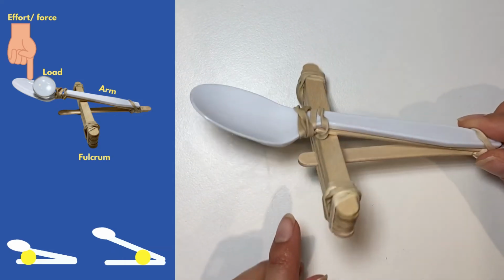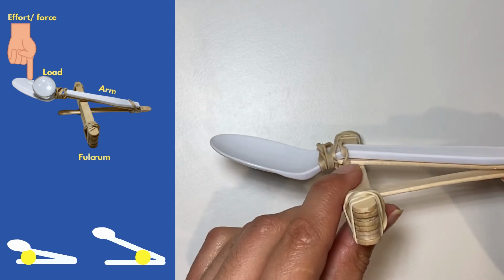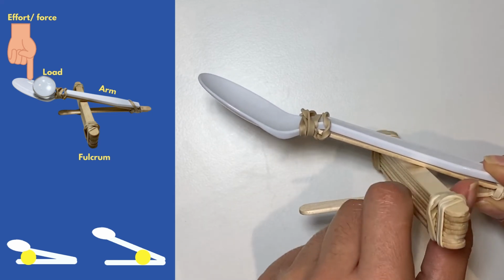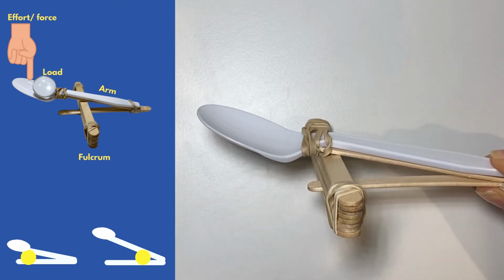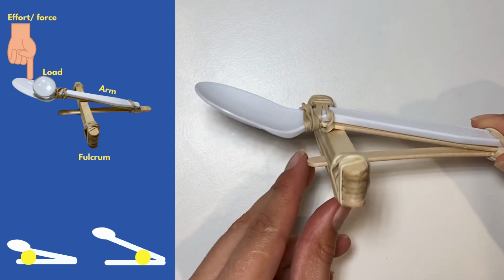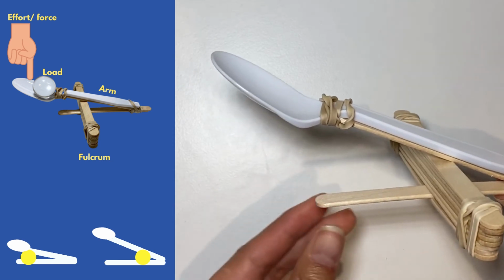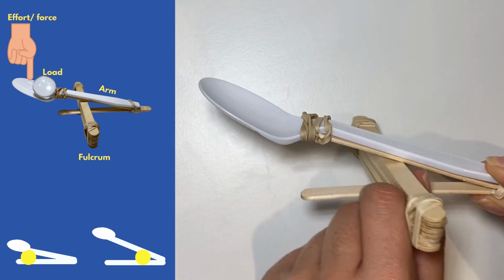Try experimenting by moving the fulcrum from left to right. You'll notice when it's at its left position, the spoon is kind of close to the table and therefore it doesn't have as much room to store potential energy. But when we move it to the right, there's a lot more room for you to push down further, which means you can store more potential energy, which will result in more kinetic energy, and your ball should fly further.